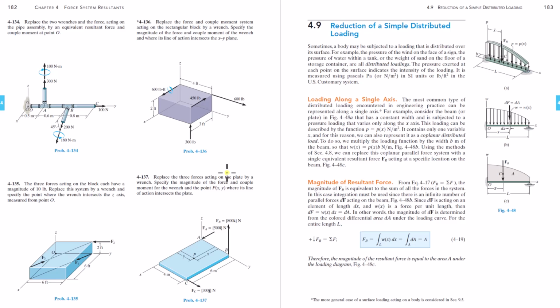And so up to this point in this course, every single force that we've dealt with has been a concentrated force assumption. Even the couple moments come from two concentrated forces. But there are scenarios where the area of contact is not small relative to the entire body that's being analyzed. In that case, you can't put a point force. You have to put a distributed load, like shown here.